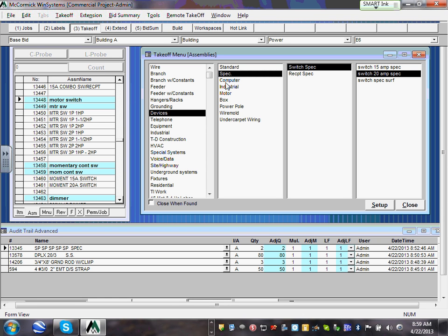They'll basically use flex conduit that's not insulated. Non-metallic? Yeah, you can use non-metallic flexible conduit. Typically metallic flexible conduit, half an inch or even less, is what they use for fixture whip.